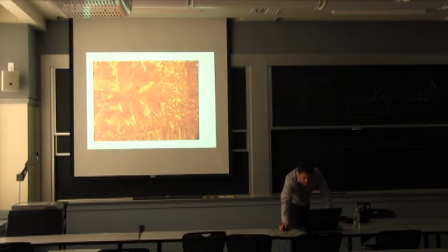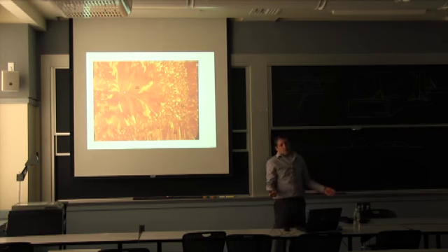So this is the surface of a billet. You have the skin here, then you transition and you have your core. So this is directional. Eventually it becomes more equiaxed in the middle. You don't want that as a part generally, especially if you're going to machine this.